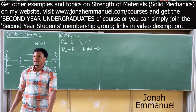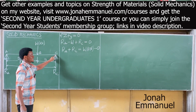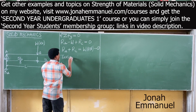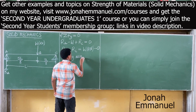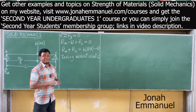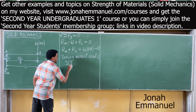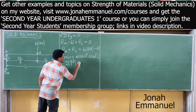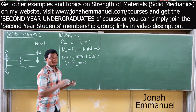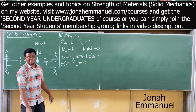As usual, what's my next task? Simple. Take moment about what there? This point. That's task 2. Taking moment about C. If I take moment about C, what do I have there? We have that sigma, the sum of moment about C, is equal to 0. And we said when it's clockwise, it should be what there? Positive. So positive moment or clockwise moment is positive.